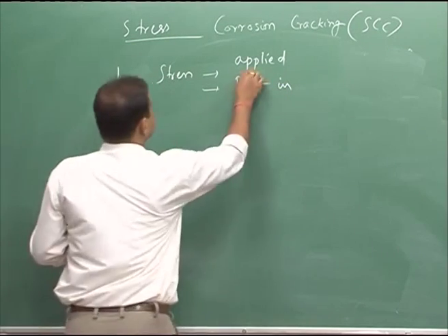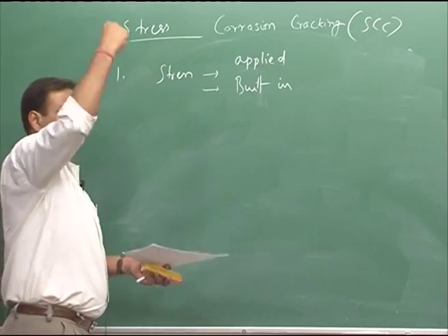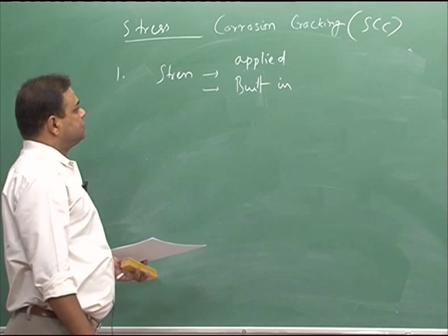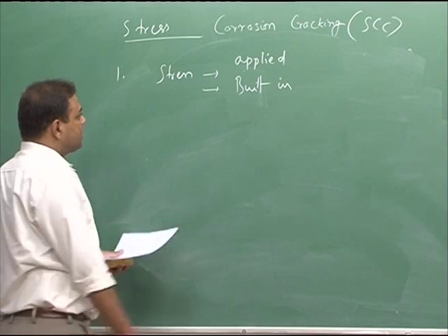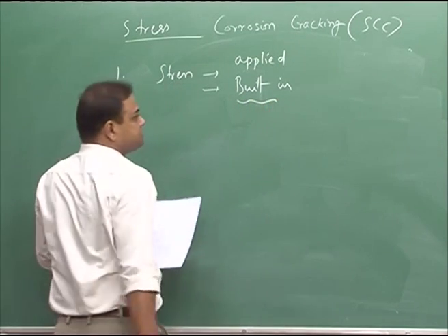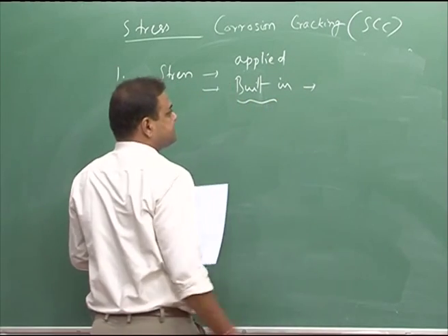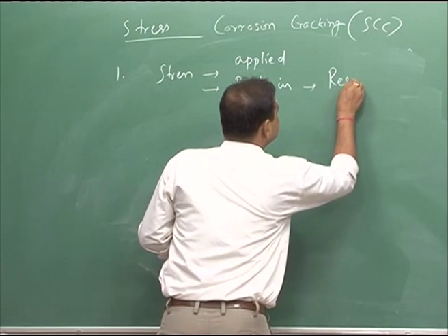Now, applied we understand: from an external source we are applying the loading, and the tensile component leads to stress corrosion. Built in stress, in many cases, is basically a residual stress.